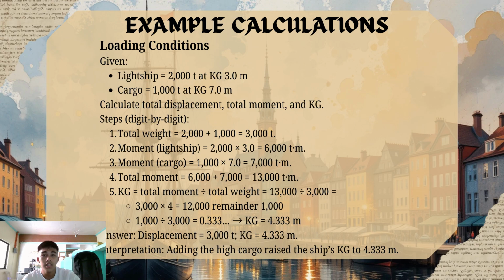So, these simple examples po, nagpapakita po siya ng kung bakit loading conditions are very important. If cargo is not evenly distributed, the vessel will trim either forward or aft. Here, since the aft hold has more cargo, the vessel trims by the stern. That's why the booklet guides us in balanced loading. So, itong example po na ito, nagpapakita po siya ng loading conditions.